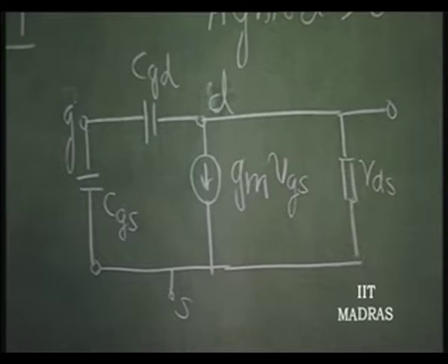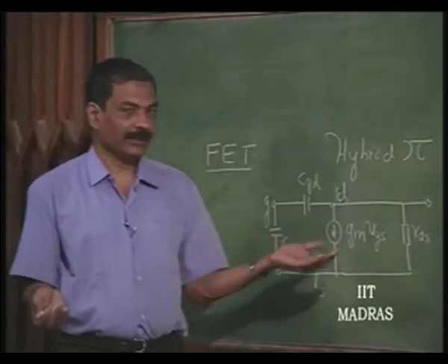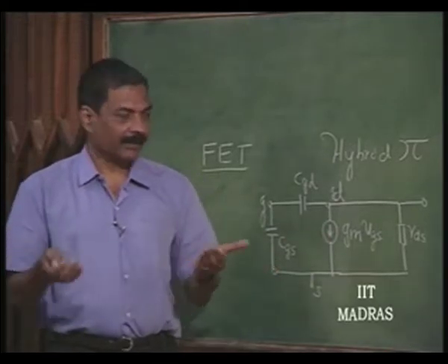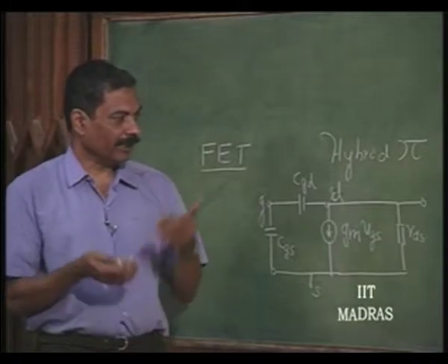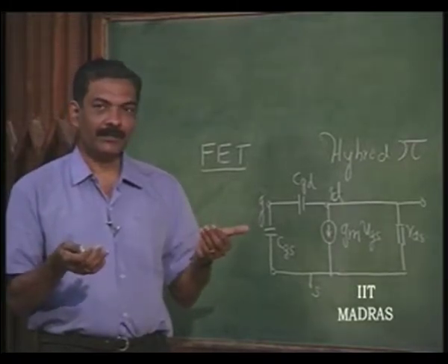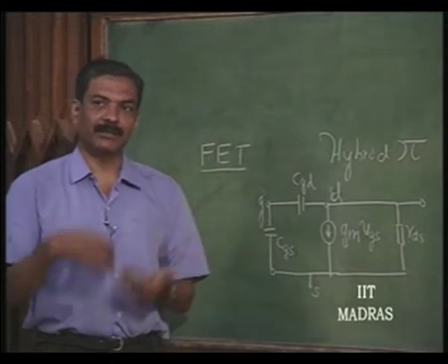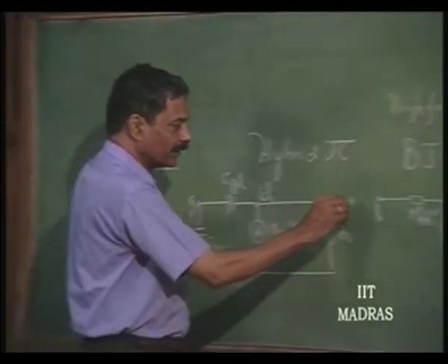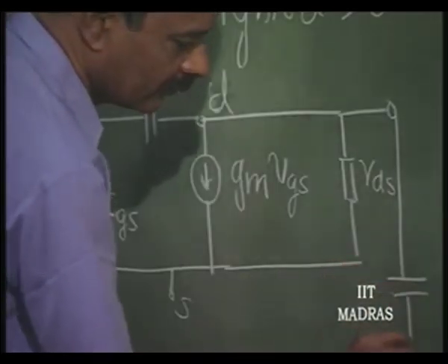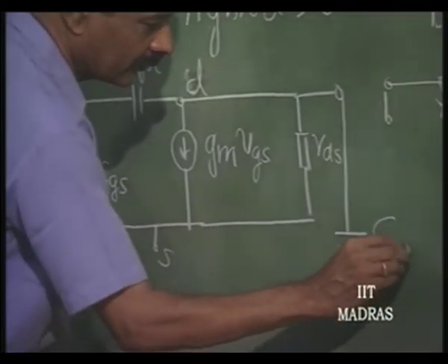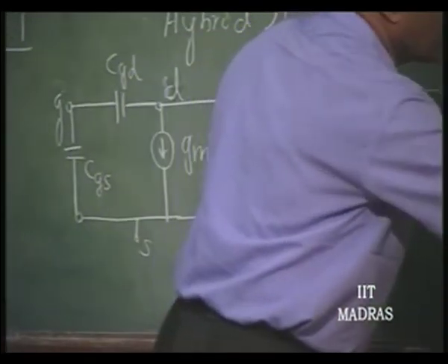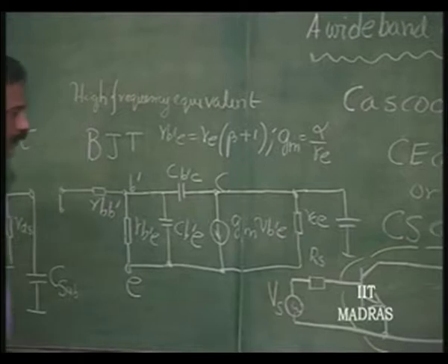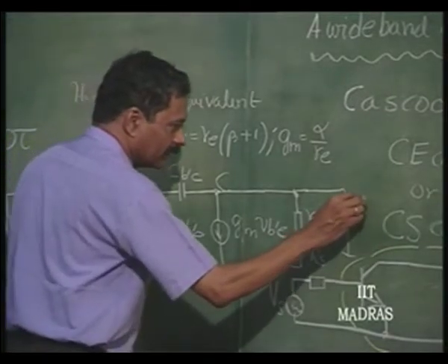If they are integrated circuit components, then these components lie inside what is called a well. A substrate has large number of wells where these devices are put, and each of these well is separated from the substrate by a junction which is reverse biased all the time. So, that is how you separate one device from the other, and therefore, there is what is called as substrate capacitance in each of these cases from this collector well, okay, or this well, we have a substrate capacitance.